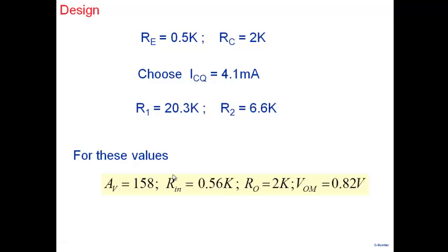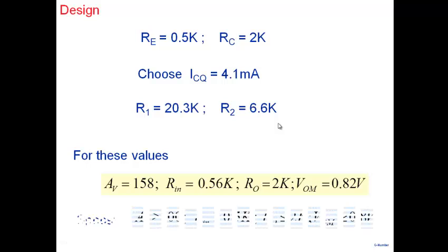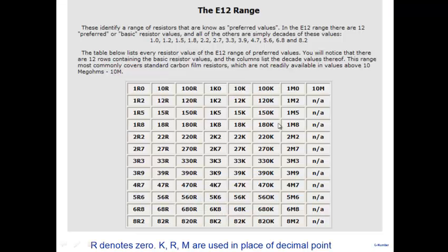And you know that in the lab, you get certain values of resistor. For example, you get, let's say, 10K, 12K, 15K, 18K, 22, 27, 33, 39, 47, 68, and all that, right? In between, you don't get values. Doesn't mean that you can't get. If you want 57K, you can always take 56K and connect 1K in series, right?